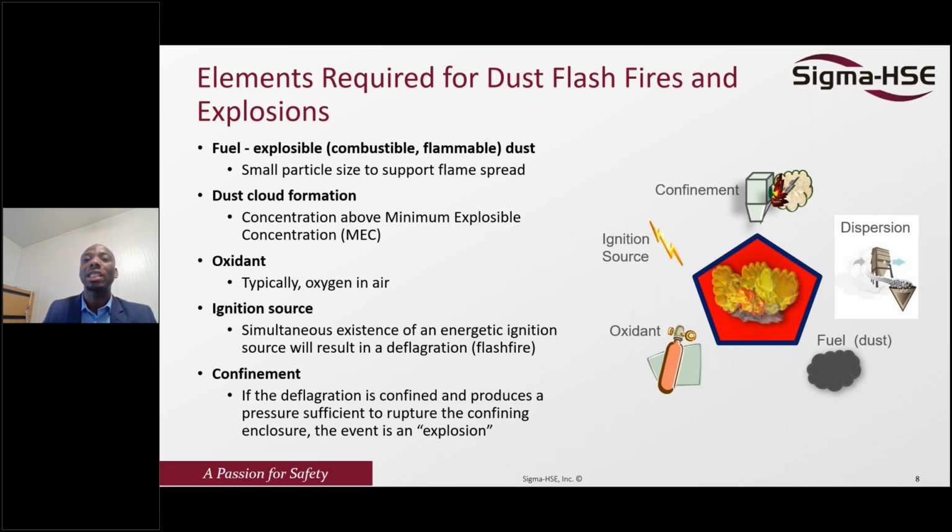So for example, if I have a fuel that is starch or maybe sugar, which everybody handles, I put it on the floor, I apply heat, and automatically I'm going to get a combustion operation. The material will ignite, but how far can it ignite? It will ignite at the immediate area and it can easily be quenched.